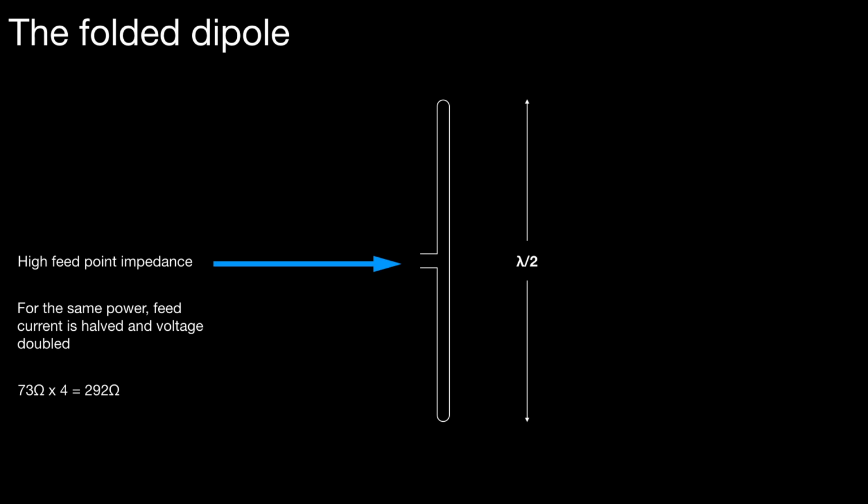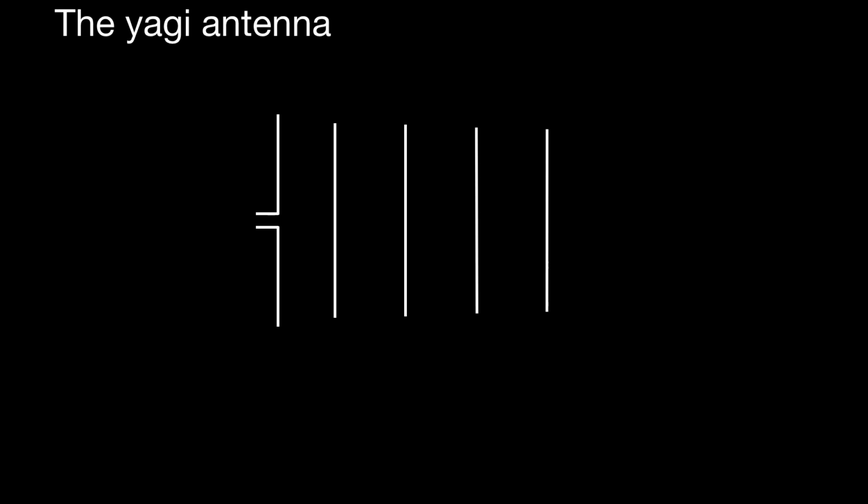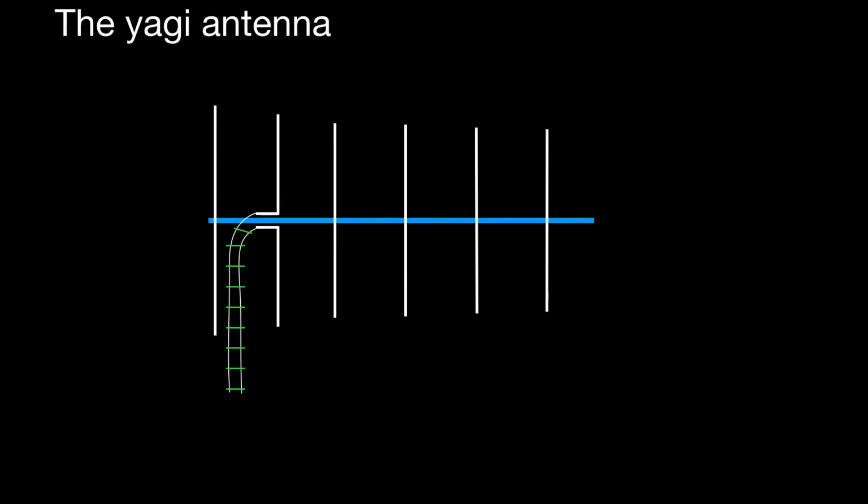The next antenna we'll have a quick look at will be the yagi antenna. There's the yagi antenna, it has a boom in the center. It has a driven element shown there with the feed point, and it has some directors, any number if you like, going forward. And behind the driven element is a reflector. The driven element is called the driven element because it's the only one that is driven by any power directly, and here we show it connected to a ladder line.